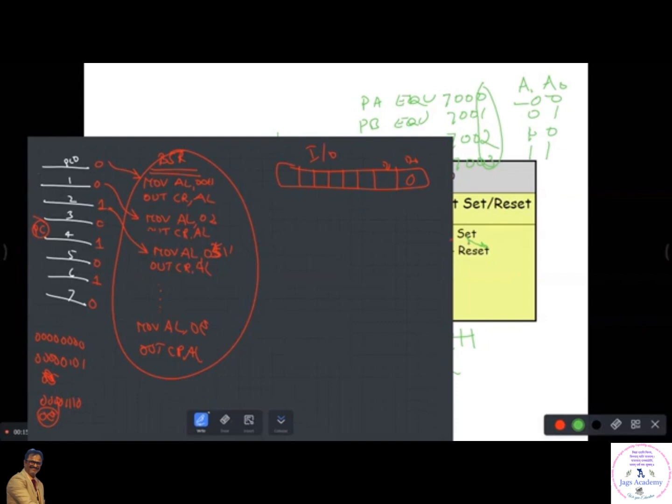Okay, then what are the others? Port B. Which is that bit? Port B, D1. See, you are not using port B here, right? Are you using port B here? No, you are not going to use port B at all. In such cases, you make it 0. All other bits you make 0. Have you understood this? Right? Except this bit. Why should this bit be 1? Because it is IO mode. Okay? Mode, this 0, 0 I will take.